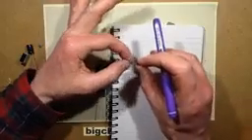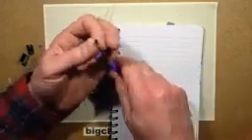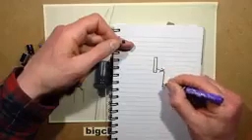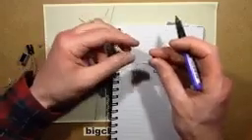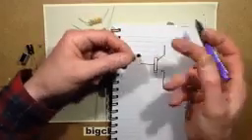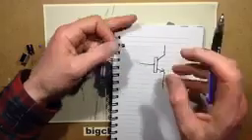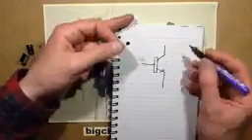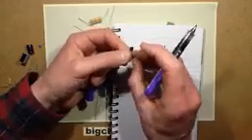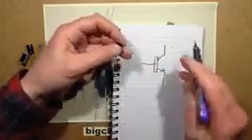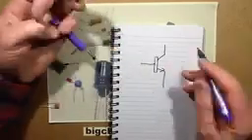And for simplicity, I'm just going to show the basic NPN silicon transistor, one of the oldest fashioned type transistors about. And the symbol for it is this. You get 3 pins, and if you ever want to find out what the pinout for your transistor is, if you're not 100% sure, just go on Google and type its number in, like 2N3904. Google it, look for images, and you'll find pictures of the transistor with the actual pin designations printed under them. It just makes it very easy to find data like that.